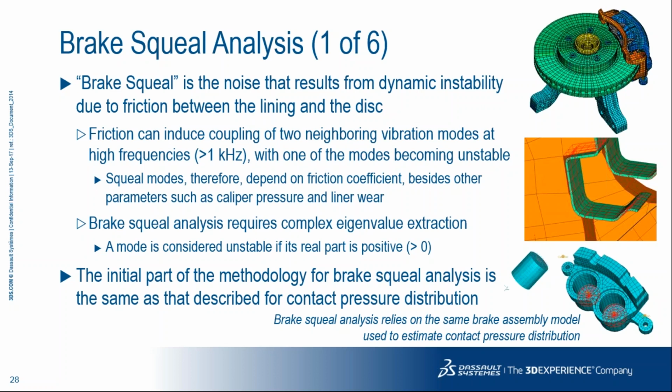One possible explanation for the brake squeal phenomenon is, for example, the coupling of two neighboring vibration modes. If two modes are close to each other in the frequency range and have similar characteristics, then they may merge if the coefficient of friction between the pad and the disc increases. So when these modes merge at the same frequency, that is, become coupled, one of them becomes unstable, and